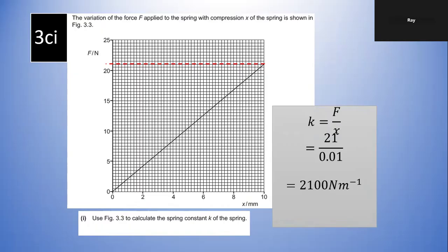Teacher, any comment? This spring obeys Hooke's law, right? This one is just to test you about the spring, that's all. They try to relate to the question later on. But this is a simple mark for you to get. Spring constant from the graph. Okay? K equals F over X. So X is the extension. Make sure you change the unit to meter. Any comment?